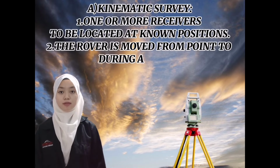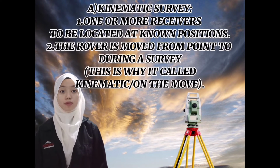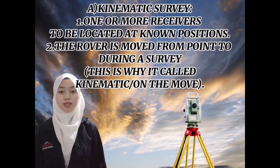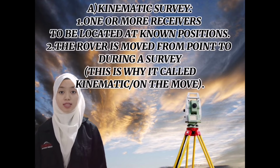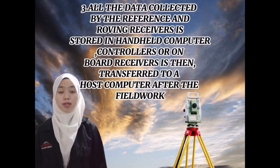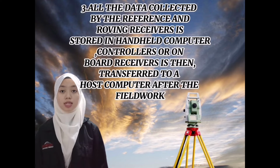For a kinematic survey, first, one or more receivers are located at a known position. Second, the rover is moved from point to point during a survey. This is why it is called kinematic, or on the move. Third, all the data collected by the reference and roving receivers is stored in handheld computers, controllers or onboard receivers.